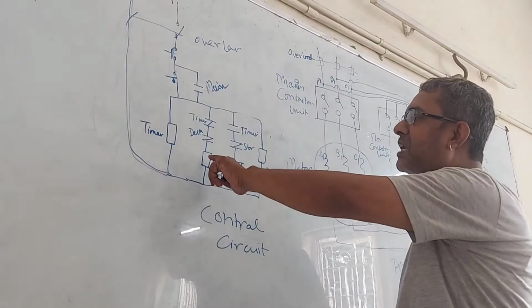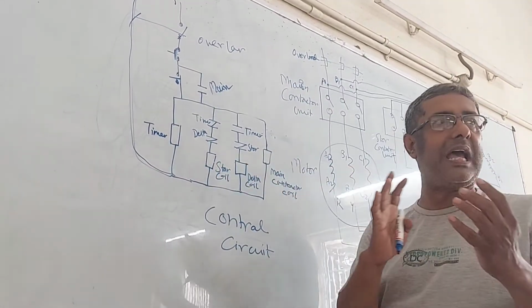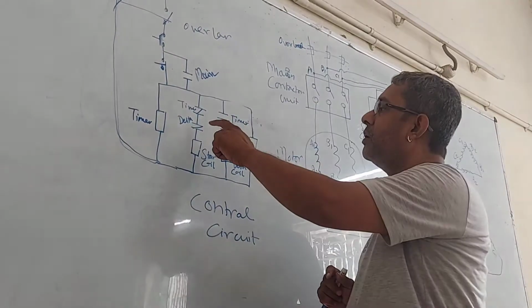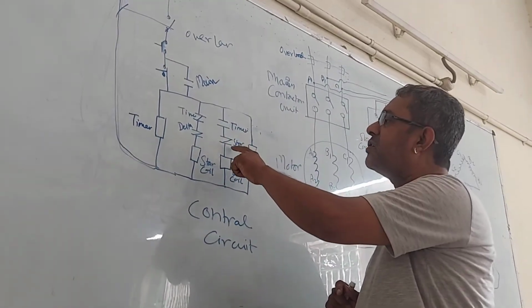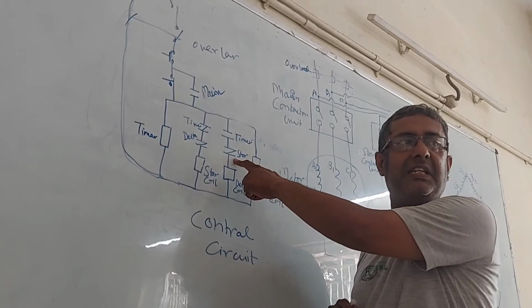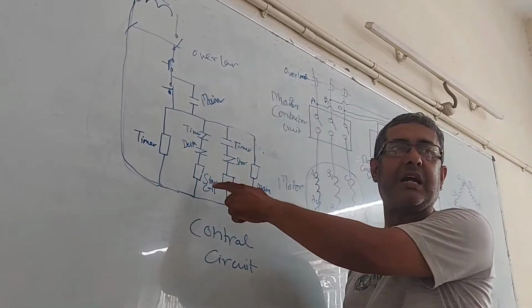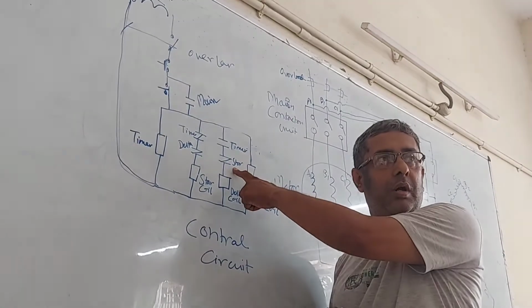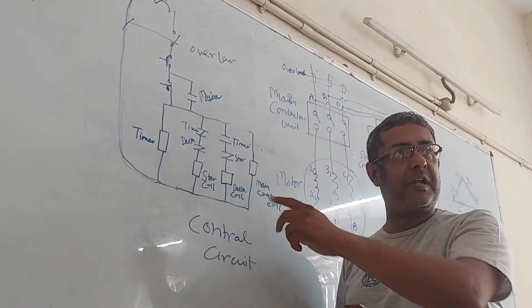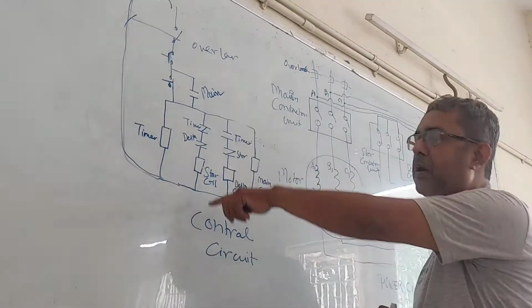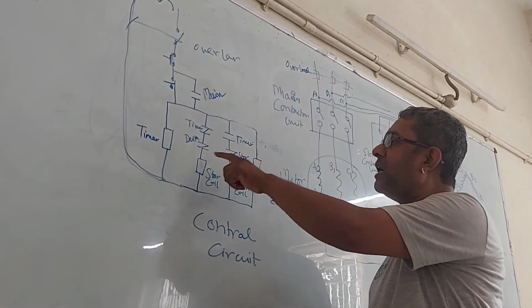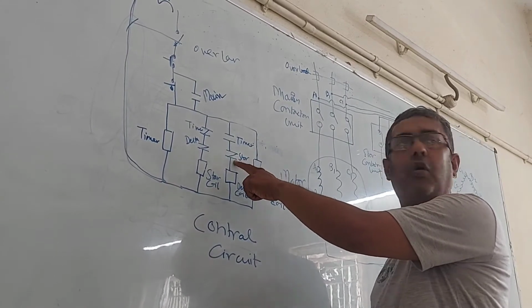Now, as the star coil has dropped out, as it has been discharged and stopped now, this contact has again become NC. Initially it was NO. When the star coil was charged, it was converted into NO. Now as the star coil has dropped out and is not being activated, the star coil's contactor unit contact will close.